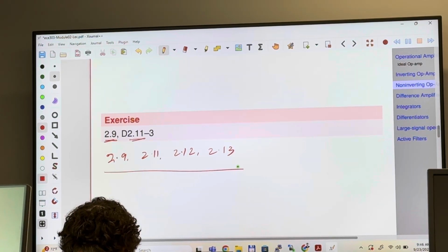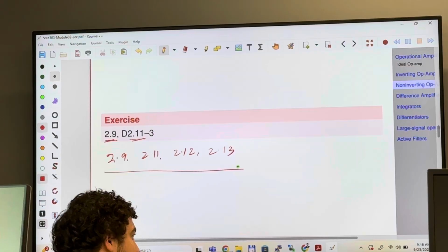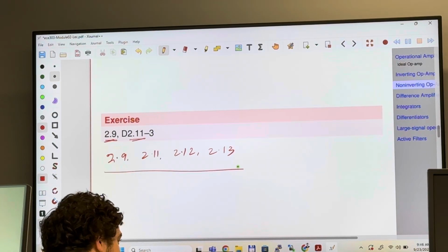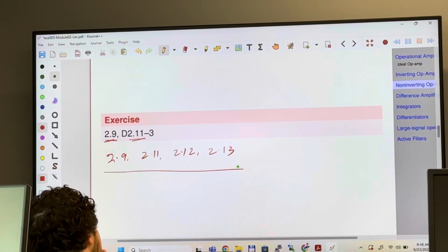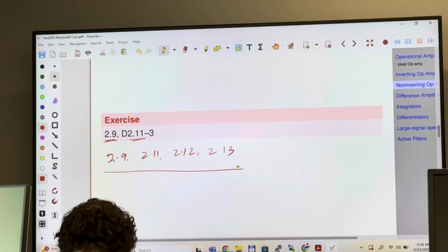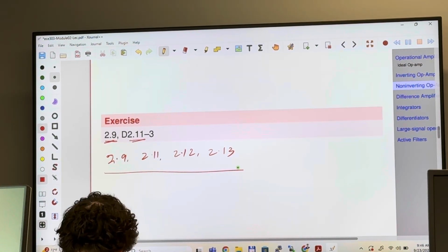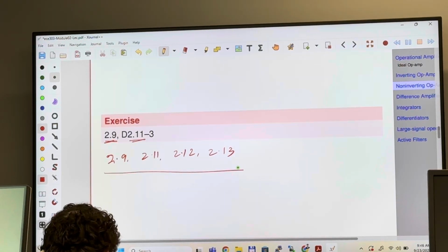And in fact, look at the function generator. You guys know the function generator, right? Right under the function generator, after the BNC connector, it's written 50 ohm, which means that impedance is 50 ohm there.